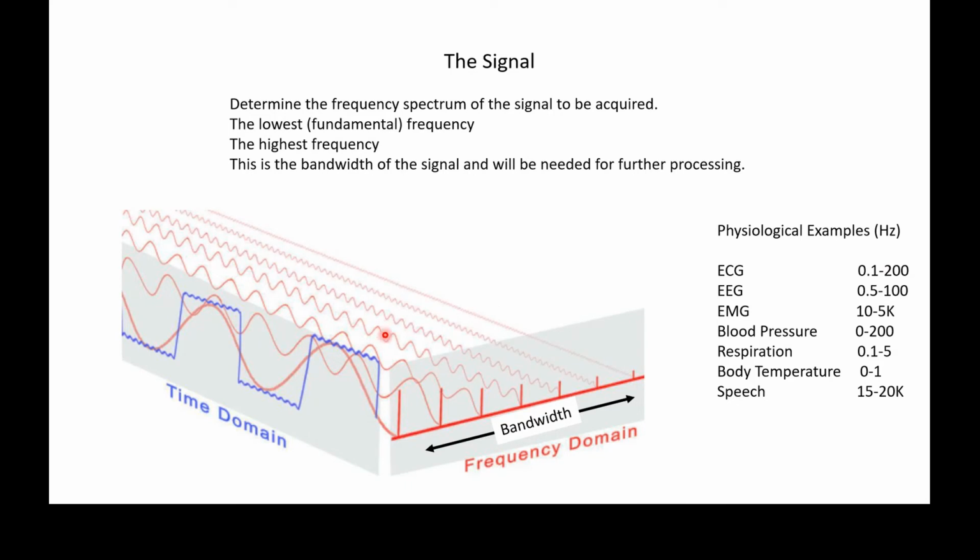And so the square wave has very, very fast changes associated with it. So you can think about any of your signals that have fast changes are going to have very high frequency components in them. And if you lose those high frequency components, then you will mush the signal so that it no longer looks like a square wave.